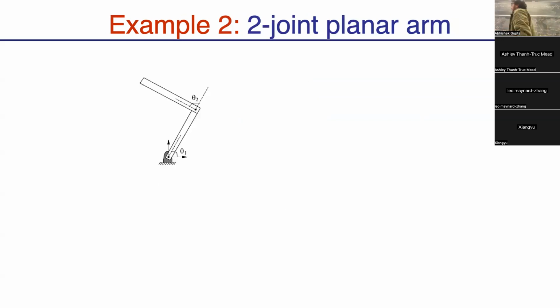Let's go to a slightly more complicated thing. You have a two-dimensional arm. What is your configuration space? So, a two-dimensional arm fixed in the plane. It moves the first joint and moves the second joint. Now you want to define a configuration space for this, so that you can define any configuration of it. What is the configuration space? So just theta 1 and theta 2.